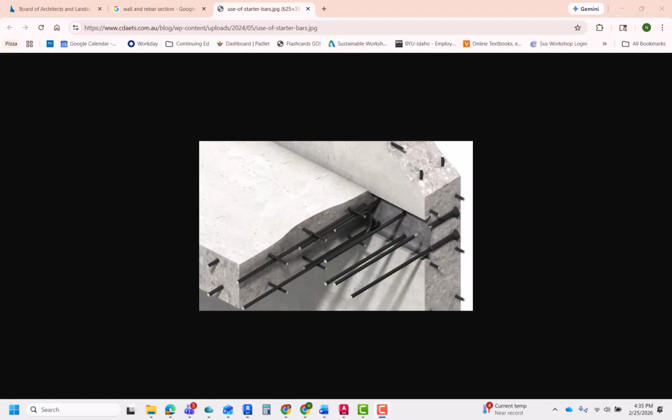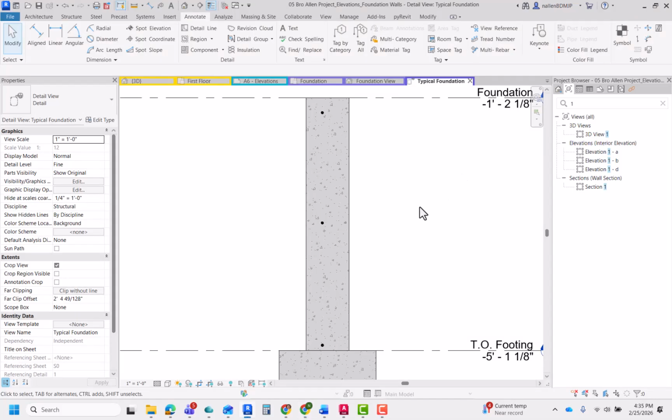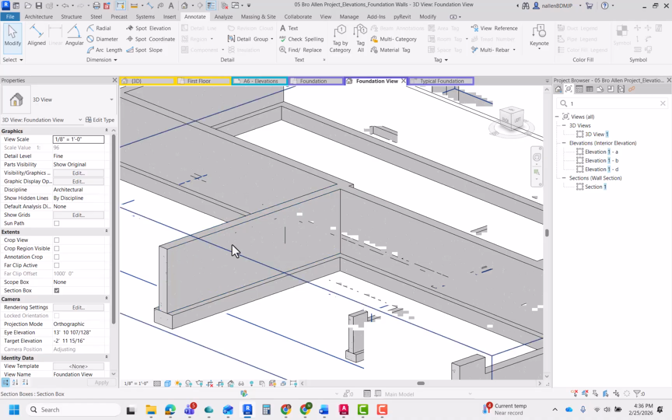If we take a picture like this, for example, you can see that there's rebar running through the concrete. And in some places, it's showing the end of the rebar. And that's all that we're looking at. Whenever we see a circle, it would be more like this instance over here, where if you looked at this face of the wall straight on, you'd see a rectangular outline for the wall, and you'd see little circles everywhere that there was a piece of rebar. And that's all that we're showing here. We've got horizontal rebar, so this runs the entire length of the concrete. Okay, it would run all the way through here at the top, the middle, and the bottom.